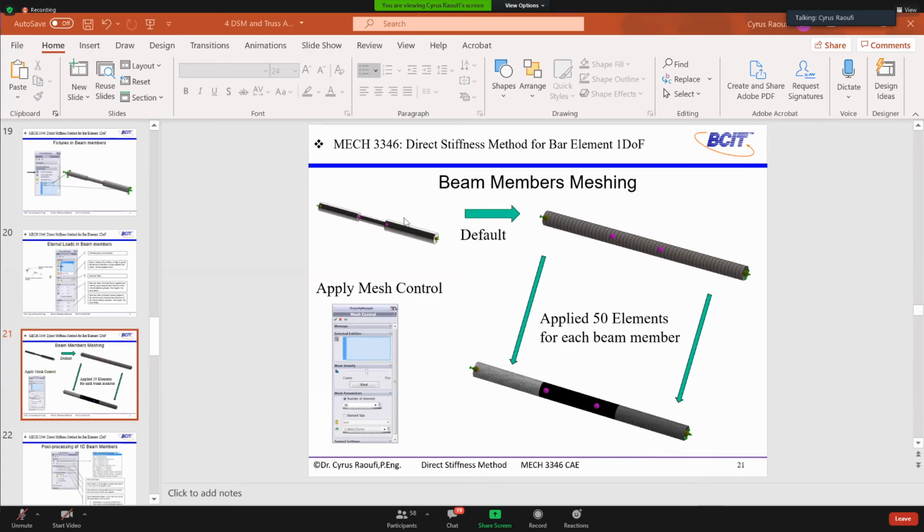But when you convert them to beams, when you treat those multi-bodies as beams, and apply mesh, this is what you see. SolidWorks is going to discretize the model, and what you see in the graphics area is this mesh. And as you see here, you don't see the big diameter, small diameter.